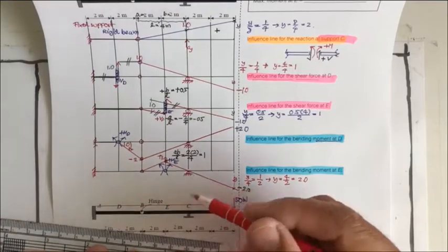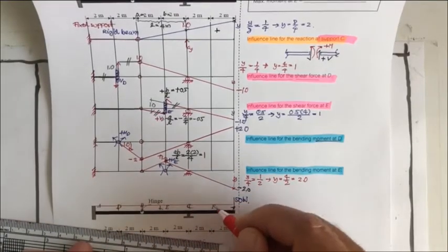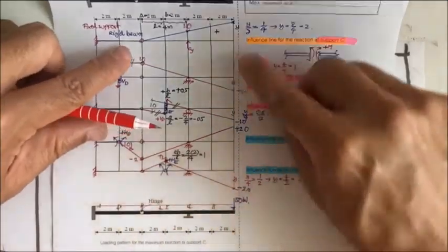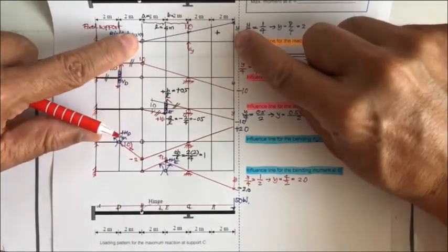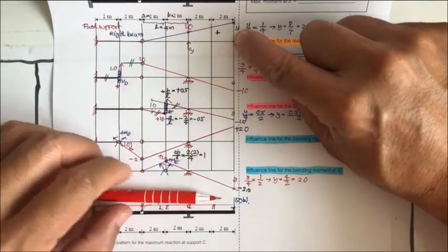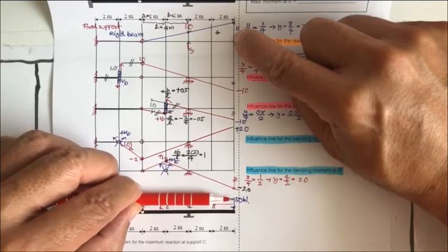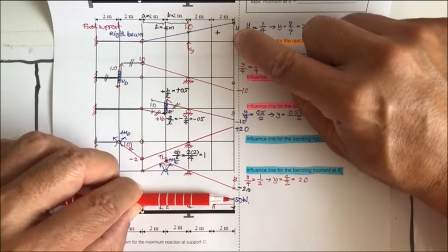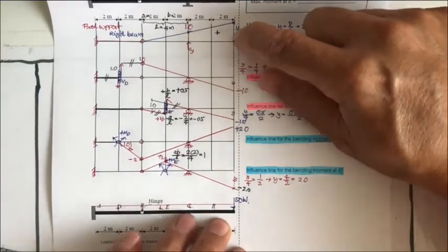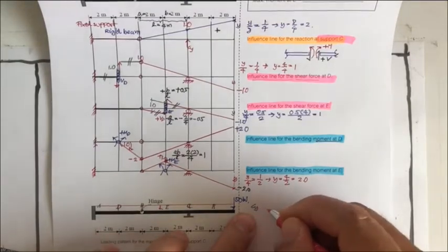And for the dead load, it's going to be along the length of the beam. Okay, unlike the concentrated live load. If we have the concentrated live load for this problem also, we will put the concentrated live load in this area. Okay, or you may put it like this on the top of the dead load. Okay, but this one we won't have, just take it out. So this loading pattern is going to produce the maximum C sub y.